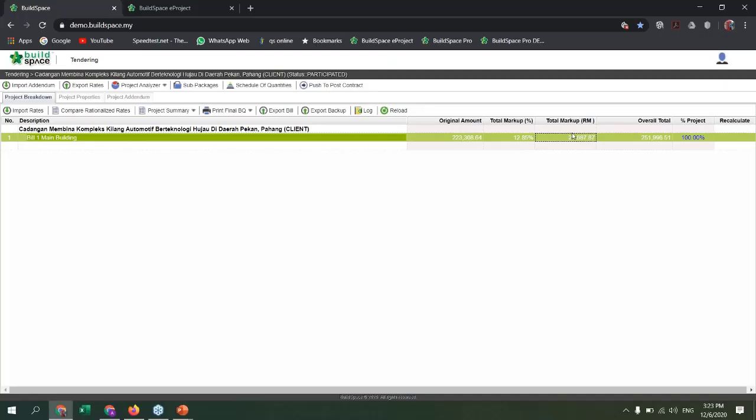So now, take for example, we already completed the pricing of the tender, and we wanted to make sure that every single item is already priced. So we can go to the project analyzer, examine the schedule of rates for the first time. Okay, we go to schedule of rates, give it a few seconds.